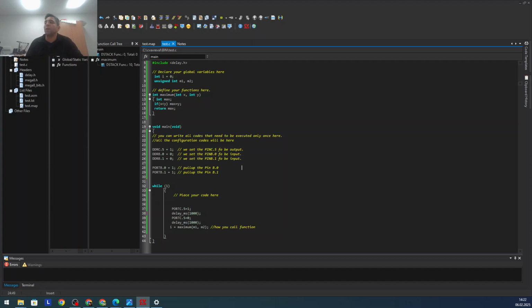And how do we determine? There's 3 main commands for it. You have the data direction register. Here you should give the value to it. Normally they are all 0, unless you turn them on here to give them value. So data direction register is this one.